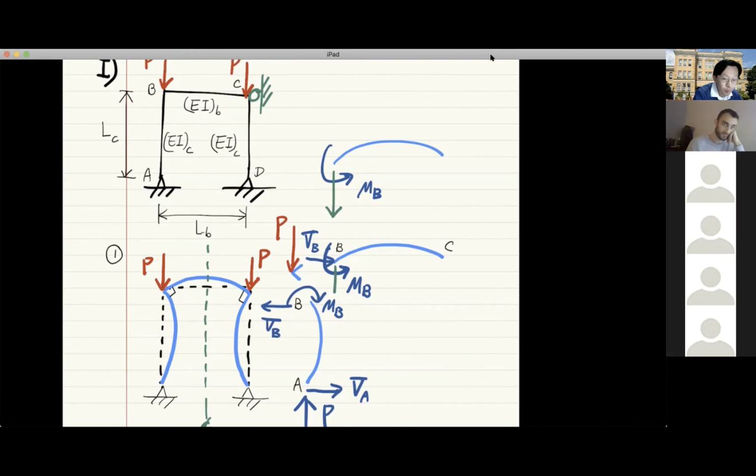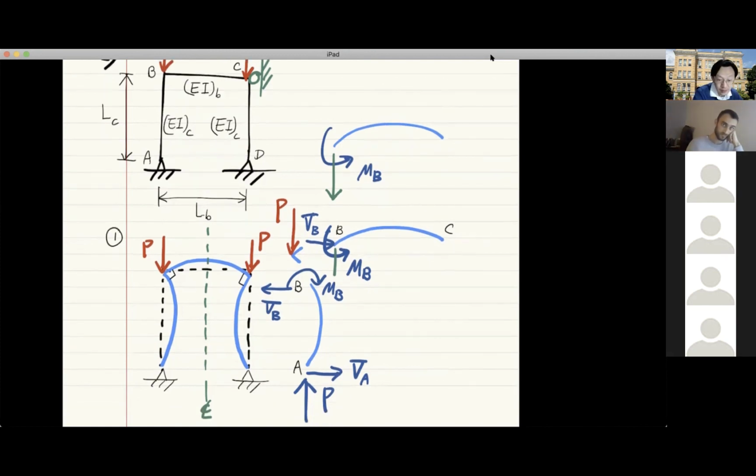So if it is downward pointing, this shear force to the member BC will not in any way produce any counterbalancing effect to the moment MB. So it cannot be downward pointing. It has to be upward pointing in order to balance it. This is just like the way we determine the direction of VA. How do we figure out the direction of VA? Because it has to be in the opposite direction of MB for member AB. Now the same logic